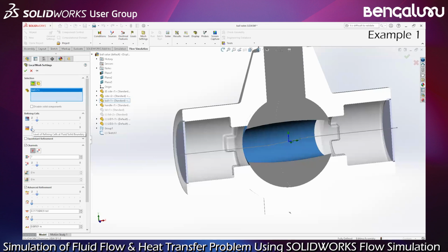And you have here the refinement of the cells which are in contact with the wall. What does it mean? With the Cartesian mesh, you can take a cell and divide it by 4. And one of these 4 cells, you can again split it, you can divide it, okay? Each time you do it, it's one level and so on, okay?